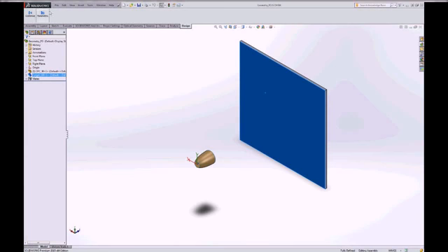But I also would like you to notice now that I am in an assembly, in addition to the optical geometry area within the command manager, I also have sources, trace, analyze, design, and project settings. And we'll talk about all of these in particular as we proceed through. But what's important to understand is that when you're using Apex, the plug-in to SOLIDWORKS, all of your components are SOLIDWORKS parts, possibly Apex-specific parts, but generally SOLIDWORKS parts.